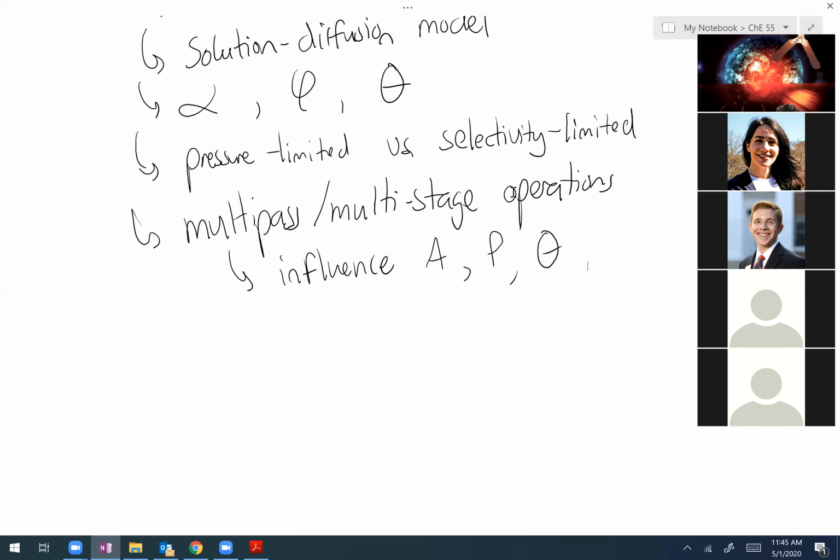Yeah, and I think some people have kind of gotten hung up on that. If I tell you something's 10% CO2, that's the concentration. It's 10% CO2. People want to think in terms of, well, what is that in grams per liter? And I'm like, well, if I'm in a gas, I really don't care what it looks like in grams per liter unless I want you to solve it on a mass basis. But for most gas systems, we can just calculate fluxes and things on a mole basis. It only gets really tricky if I give you something in weight percent. Then you can be like, well, do I need to convert? Or can I make it work?